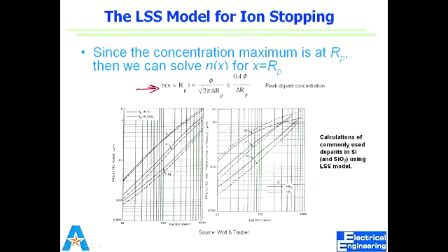Does it make sense? So you can use a bird's beak to get something like this, where you have a graded profile, right? Because we want a graded profile in many applications, where we don't want an abrupt profile. In that case, maybe you want to play with that and get different energies of ions when they enter the substrate. Make sense?